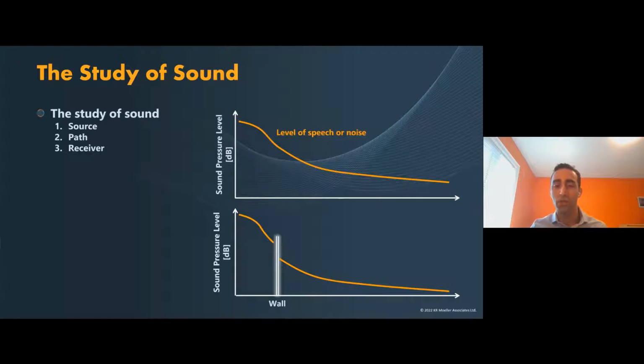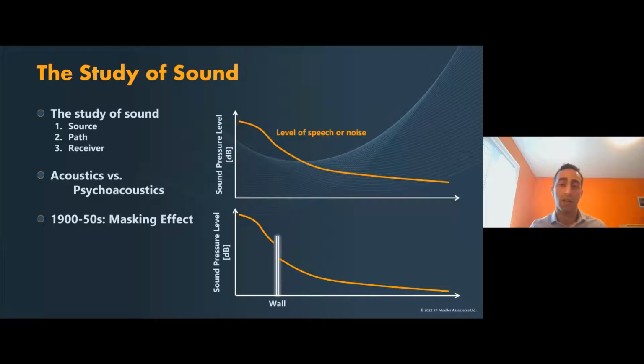This is important because acoustics is most often understood to be in relation with the person when it is not. However, in our previous examples, we've shown an interest in understanding the effects of sound and noise on the person. The study of the perception of sound and the associated physiological effects is known as psychoacoustics. What may be the most important principle tying acoustics and the occupant together is a principle known as the masking effect. Trust me when I say its importance is extremely understated.